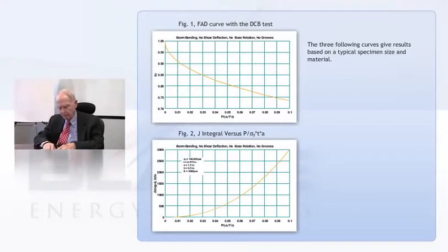The next three are dimensions of the standard dimensions. And you know, when they do that on a standard, that's sometimes an indication that if you change the size of the specimen, you might change the result. And that's kind of true here. So they have a standard size, and of course, Young's modulus, you take what you get.